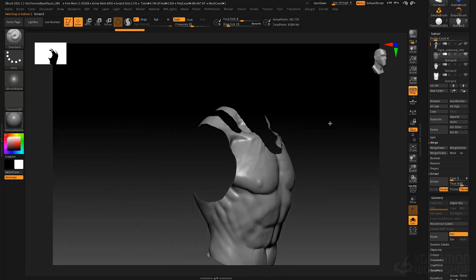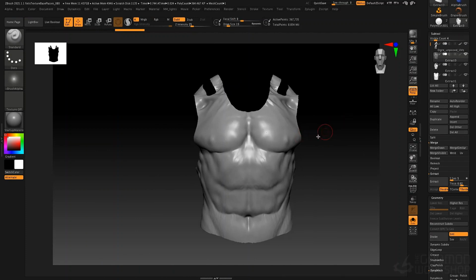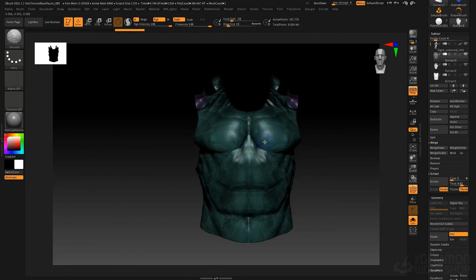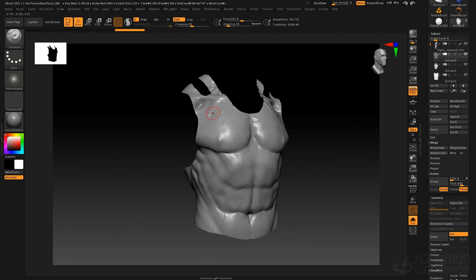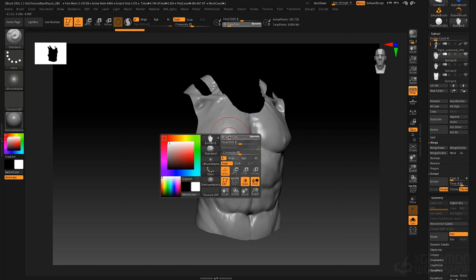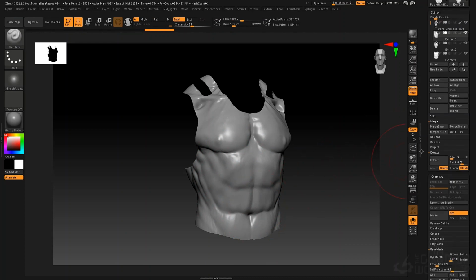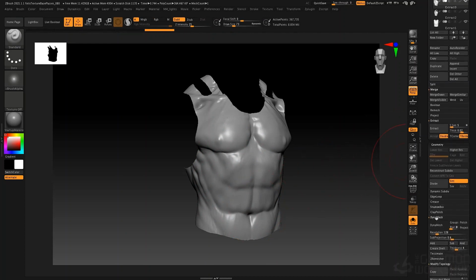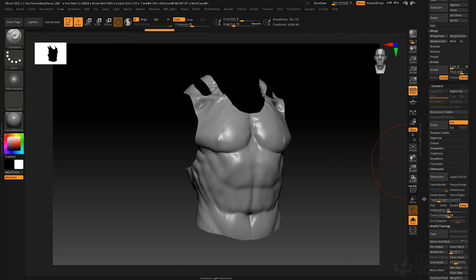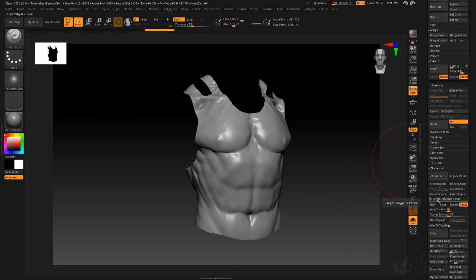So now, the easiest thing to do is you could sculpt on this, but it's going to be quite dense because of how dense the mesh was we extracted the mesh from. What I like to do is retopologize this. Now, I could keep this pretty dense if I wanted it to be like a form-fitting garment. I could smooth out some of the surface details. But what I'd like to do is go to Geometry, Z-Remesher, and we'll Z-remesh this. So currently it's 300,000 faces. We will set this to 10,000 faces and Z-remesh.